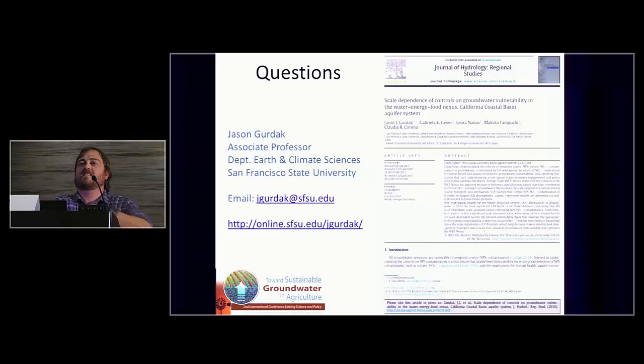Jason, interesting to see the variability in the dissolved oxygen levels and redox conditions in the dataset. My question is, do you see that variation also if you look at the different depths? Because I assume all your wells are across different depths in the analysis. Did you try to separate them, up to a certain depth and then a bit deeper and a bit deeper, and do you see any gradient in dissolved oxygen? Because it's interesting to see in some cases deeper water is reduced or low in dissolved oxygen, and not probably the case here, but in our systems a lot of water flows quite horizontally over the top of the shallow water, which still is oxidized and takes nitrate.